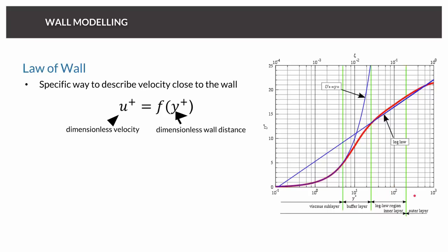And what I can do now is, instead of resolving, let's do a stop here first of all, because this is very important. So there are two aspects of wall modeling. The first one is that I need to properly resolve the boundary layer. And usually this would mean I need to spend a lot of cells there.